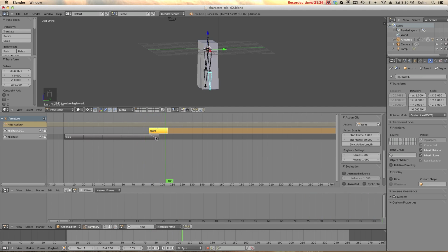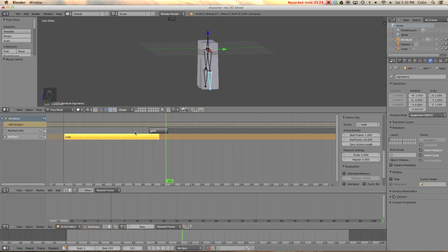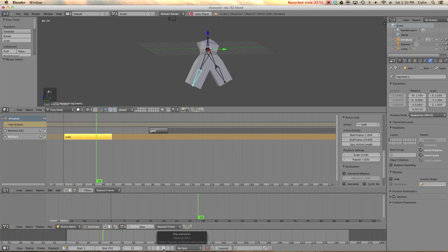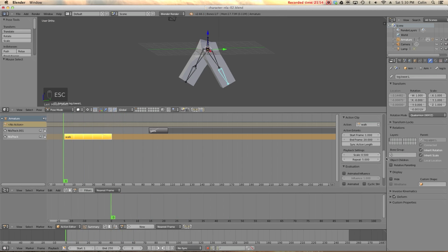Okay. One thing I forgot to mention was that if I select a block of data, and let's say he's walking along, and I want him to walk a little bit faster or a little bit slower, I can do that really easily. Right over the repeat option is the scale option, and if I change that from 1 to 0.5, every walk cycle will take half as much time, which means he'll be walking faster. So if I play this back, he's walking twice as fast. Maybe I'll select that and go to scale 0.75 to make him walk a little bit faster than that.